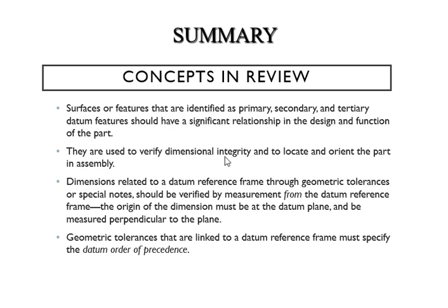Integrity means the dimension has to be correct, when you build and when you draw. And also we want to know the orientation and location, so therefore we measure from them. So all the dimensions related to your datum reference frame, you're going to put in a special note.